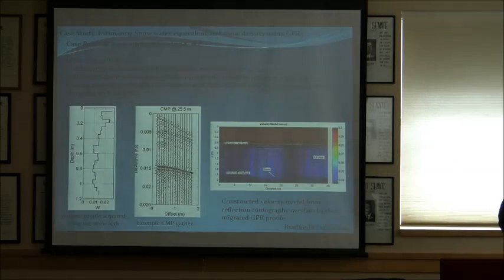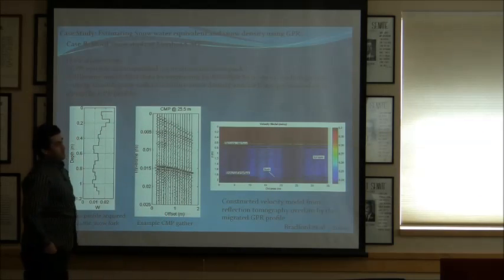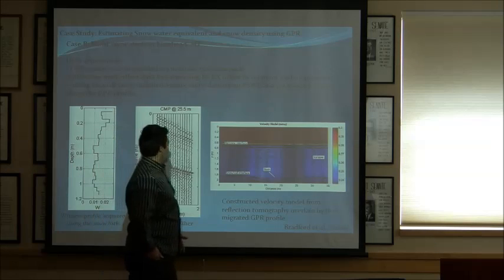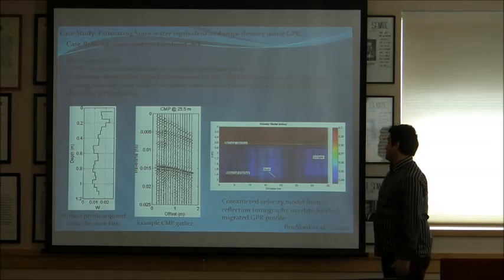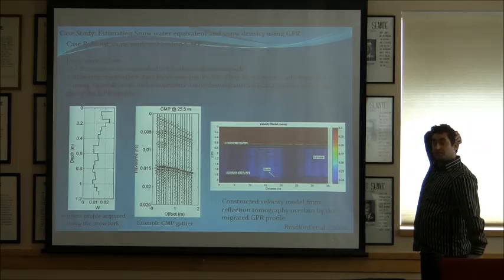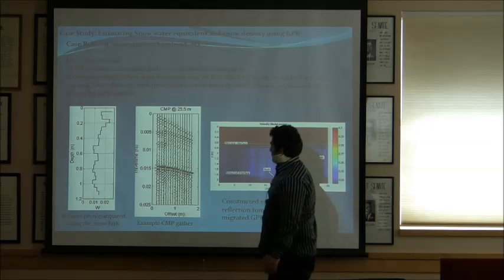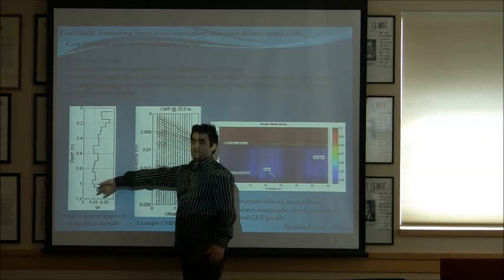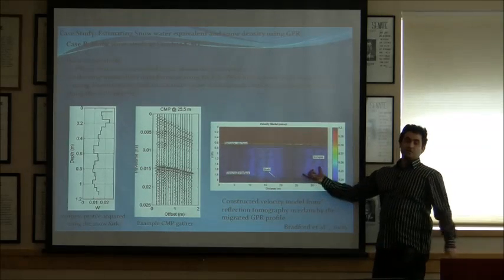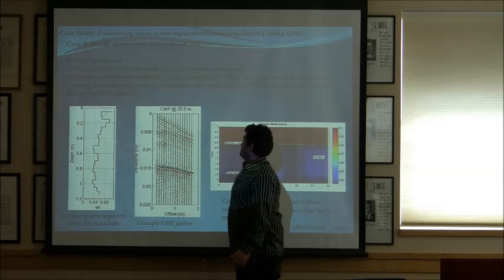Okay, so that's interesting. Case B, if you have a complicated scenario, if you have water there, you need to measure another quantity, the attenuation of the radar signal. Again, those guys give a set of relationships that you can easily follow. Those people use the snow fork at some location along the profile and calculate the velocity model from reflection tomography, very straightforward. And here is an example of a CMP.